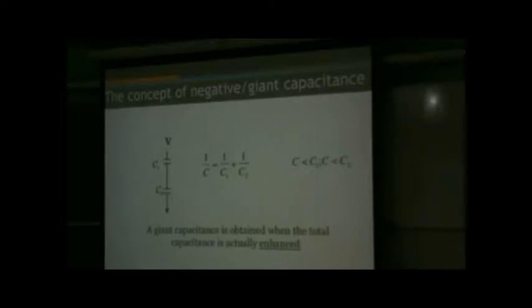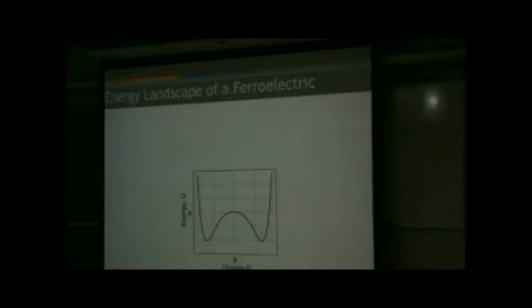And if the total capacitance in the network will go up, then at the middle node, the voltage will be V minus Q divided by C. But C is now negative, so the internal node voltage will be larger than the supply voltage. Okay? We are not doing any energy amplification. It's just a voltage amplification. It is like a transformer. From your primary to secondary, the energy remains the same. It's just the voltage is going up. All right. So, the question is, how is that possible?